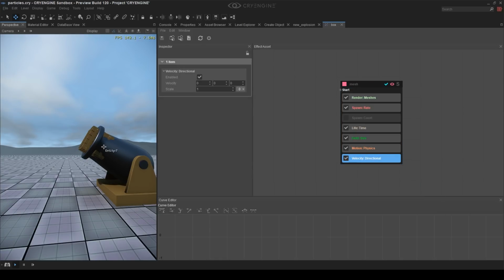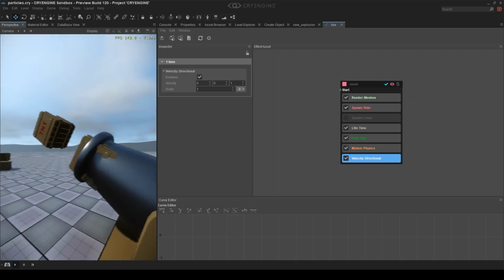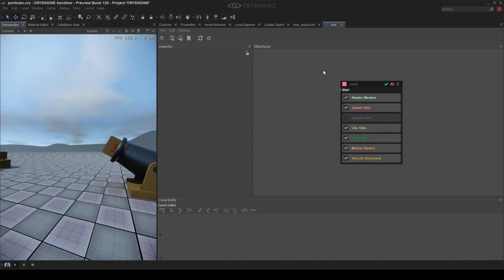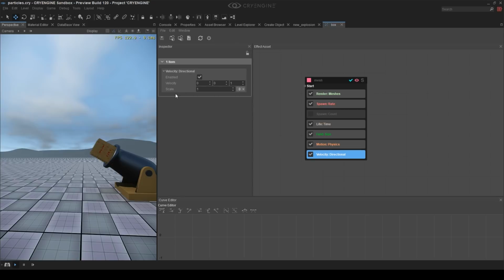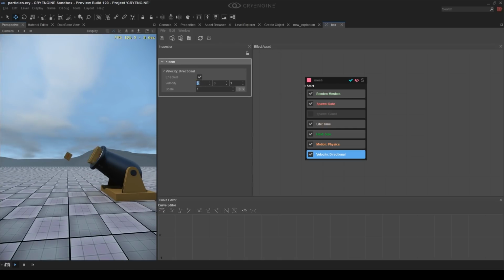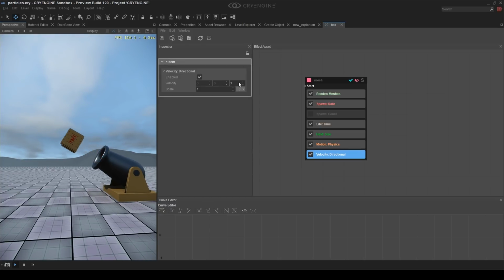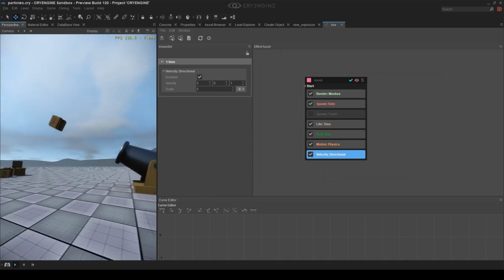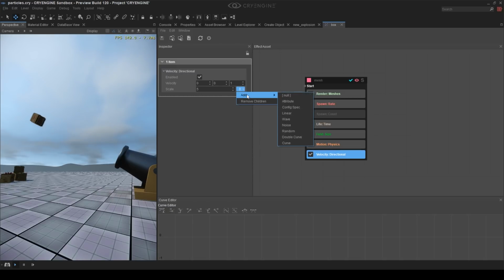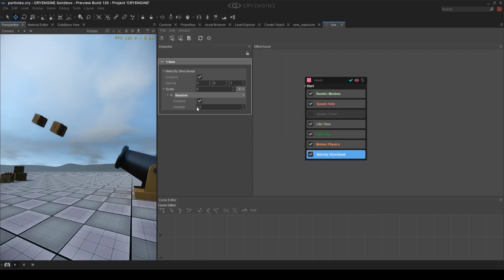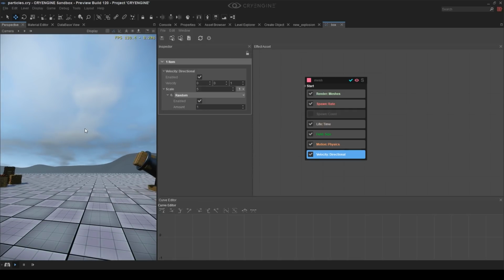And it's gonna be just directional, and it was z up, and the directional is always just in the parent space. Which means at the moment the entity is the parent, because this one is not parented to anything. How this velocity works here is basically you just give a vector which can be normalized but doesn't need to be normalized. It can be any value, so you can have 5 to the side but also 1 forward. I usually leave this at 1 and then just scale the vector. Because on the scaler you can do the modifiers, so you just have a random 0.2, or 1, so it means it's not always the same speed.